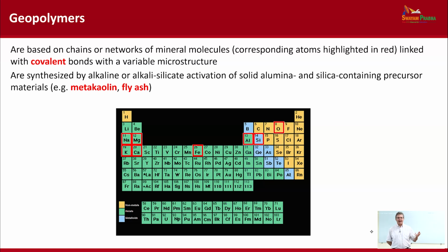If you take kaolinite and heat treat it to, let's say, 700 to 800 degrees, you are at a temperature too low to start forming mullite and liquid phase, but you decompose completely the structure of the clay, and you dehydrate the clay, leaving a material which is amorphous and highly reactive.